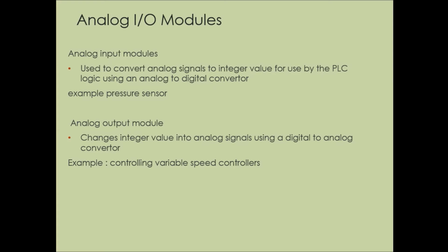What happens is, when we only have one bit that displays 0 or 1, that's not enough resolution to indicate that there is only half of the voltage. So we use an integer value. We can use 16 bits to display 0 to 10 volts, and when we have 5 volts, we'll display 5 on our integer value. All we do is add more resolution to those zeros and ones in order to obtain a value or a range of values.